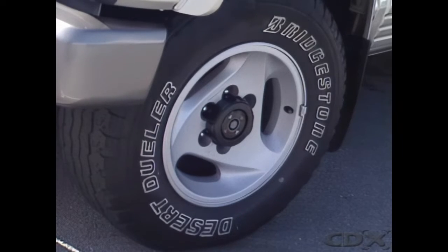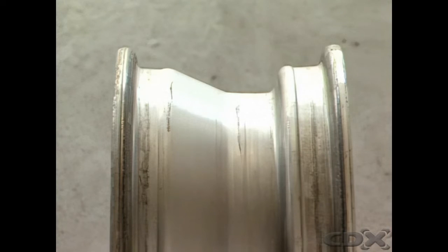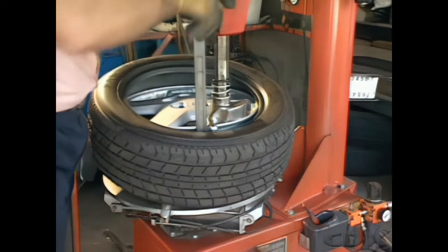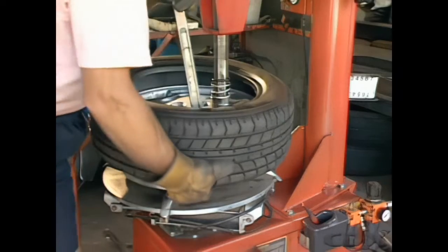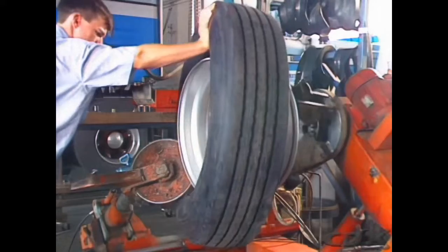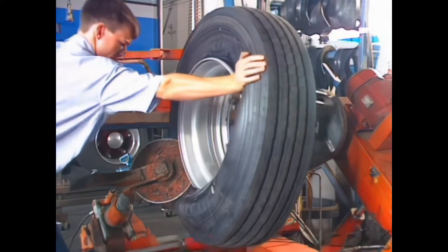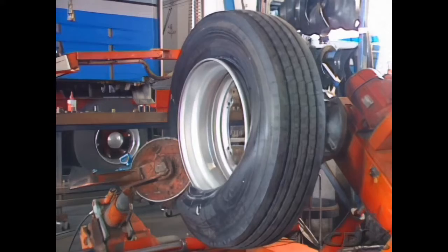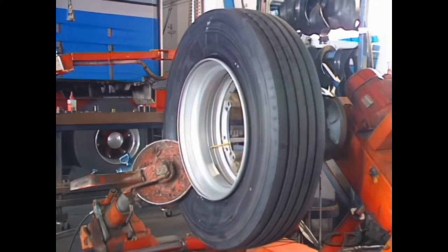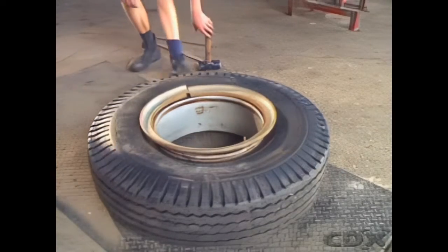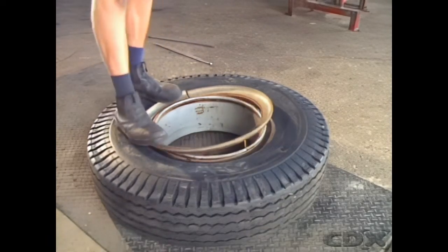Most wheels have ventilation holes in the flange so air can circulate to the brakes. Most passenger car wheels are of well or drop center design. This design allows for tire removal and fitting. Tires for heavy goods vehicles are much stiffer, but they can also be fitted to a well-based rim or to a flat-based detachable flange rim, depending on construction.